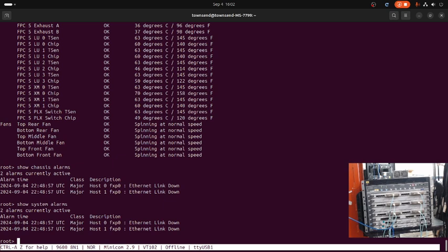There we go. So guys, this is how you basically estimate the type of power supply that a chassis like this requires based on the configuration of the line cards. This one consumes a specific amount of watts. This one as well, this one as well, and the whole chassis. It is very important to check and send this. I have this document ready to send to my customer, because he needs the information. It's very important for them to estimate the total amount of watts of the chassis.